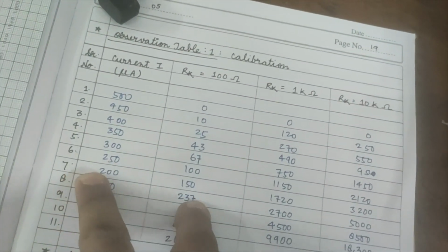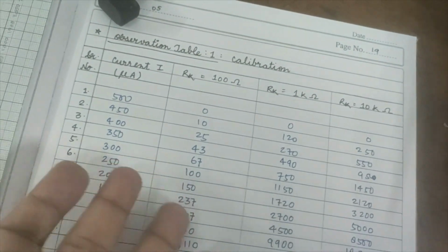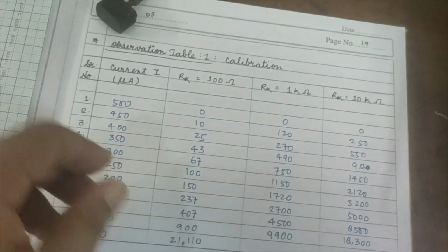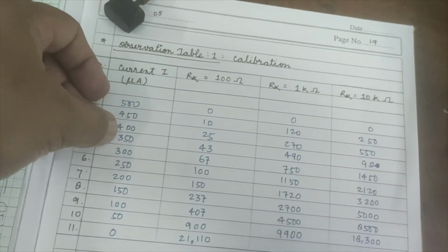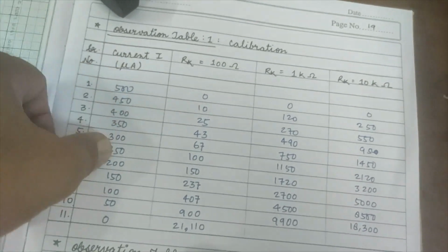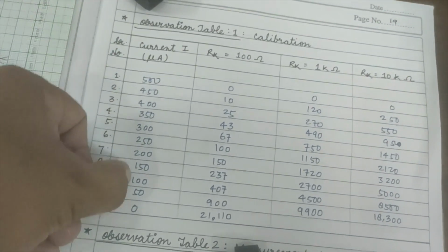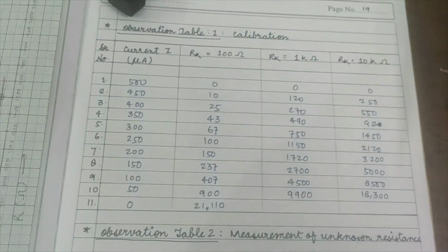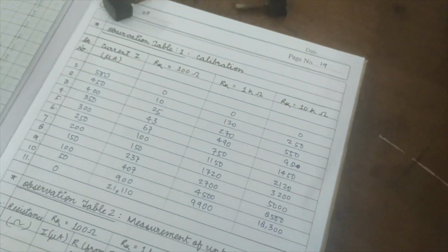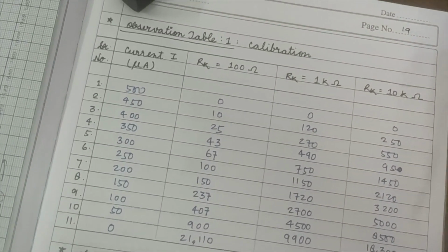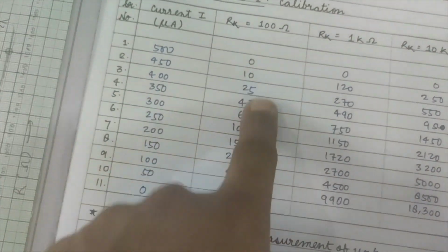If both of these are very variable, the plotting becomes slightly difficult. So it's not necessary to use 500, 450, 350. You can choose any value of resistance, but you have to decrease it gradually so that it goes from 500 to 0. Once you do this, you have to plot the value of current I against the resistance RV.